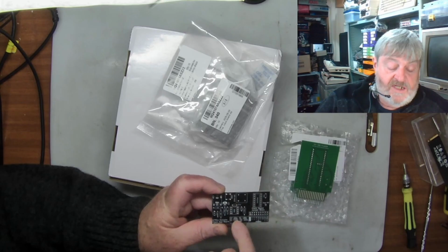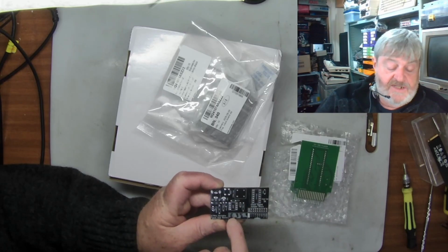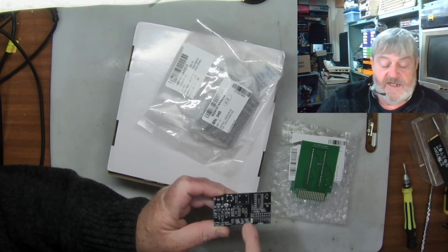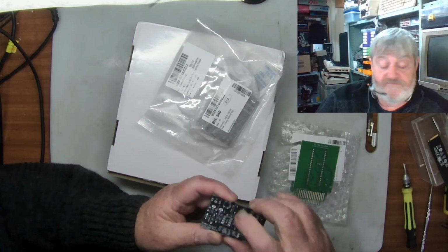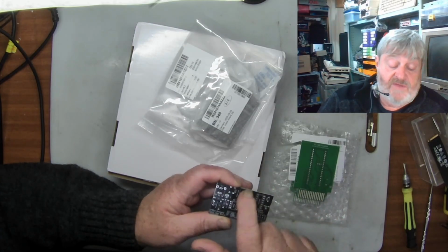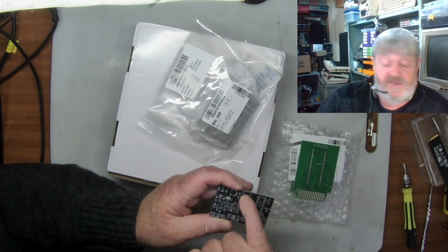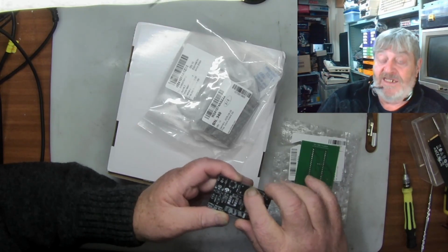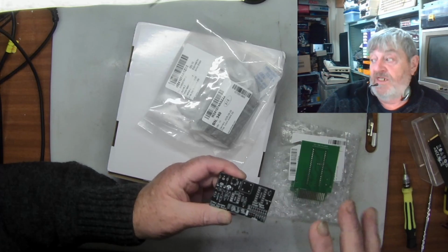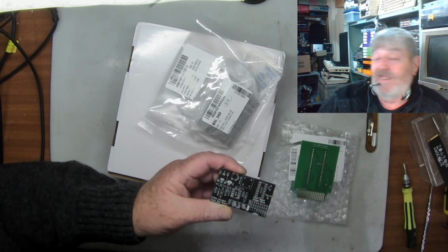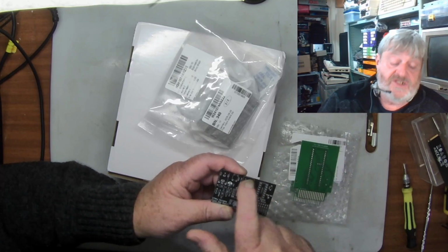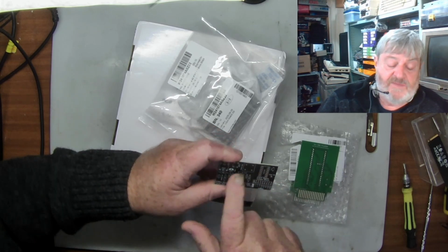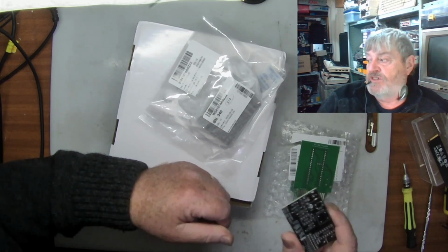These boards I have on here have dividers on them, and on here it's using the 57 megahertz clock. It tells you what frequencies it's running. You can change the crystal to whatever you like. You can put whatever you want in here. I did that because it was the best one I could find for the frequencies I want, and this is the DIP 8. You could probably work in a DIP 16, but I couldn't find any in the frequency I wanted, so that's why I changed it to a DIP 8. I could have put a DIP 16 on here, the standard ones, but it's just room on the board, and I wanted to make these as small as possible.